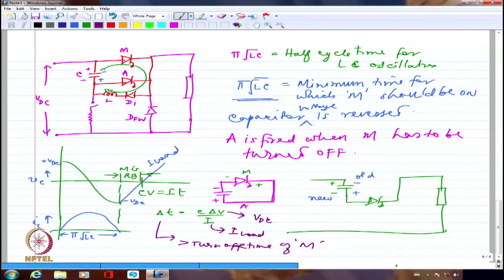In most of the motors and other things, we do have the current oscillating very slightly, because we will try to make the frequency of the chopper quite high, so that it will not have sufficient time to come down and go up. So it will just go through like this, with very, very small oscillations. We will anyway look at choppers also. So everywhere machines will creep in a little bit, not too much, but yes.